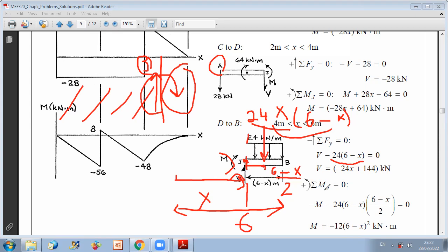For the bending moment, you do the sum of moments about the section point equals 0. If you consider counterclockwise as positive, since the bending moment convention is positive to compress the upper part, you take it here clockwise. So you put minus M, and for the distributed load, which is replaced by a concentrated force, the moment created about this point is also clockwise.